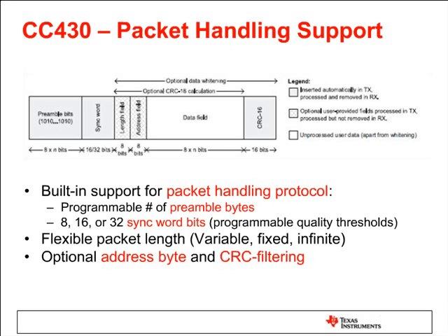So you can take, for example, your network protocol is never going to have more than 10 bytes in a packet. You can set your length field such that if you receive a packet longer than that, it's not going to wake up your MSP430 and say, hey, I received a packet. It's only going to put into the FIFO the packets of length 10. You can also set it to infinite length. You can set it to a maximum length. Very flexible. Address, I think, makes sense. It's either addressed to you or not. And the checksum, it either passes or it doesn't pass the checksum. So that packet handling support, I think, is a very, very nice feature.